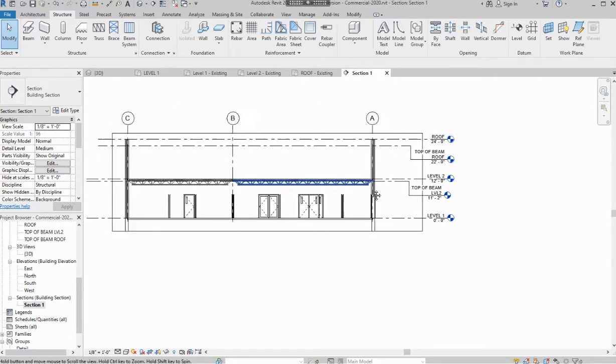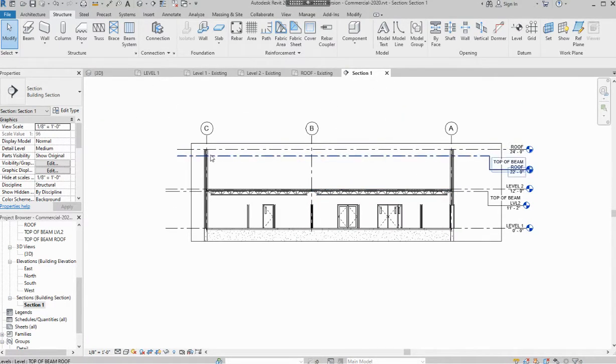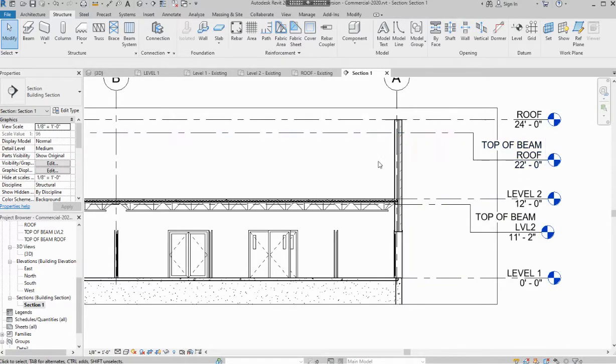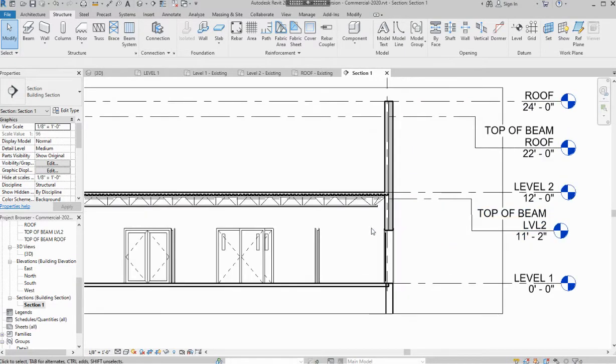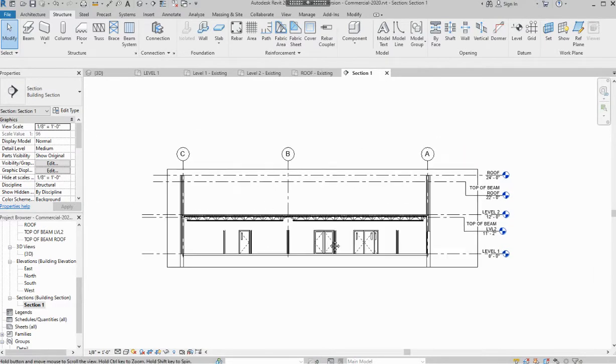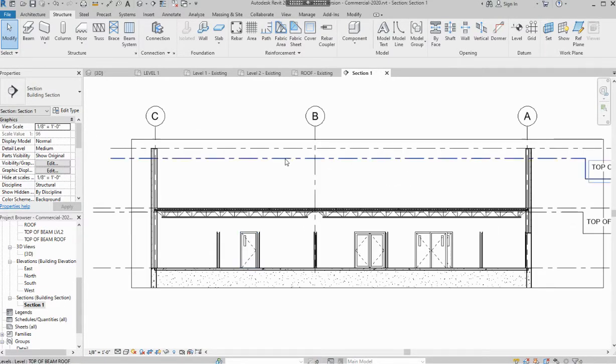So I'm going to let you figure out how to place the roof system up here based off of using top of beam and getting things to line up. And then there will be a video that shows you how to create the insulation. But exactly the same process that we used to place this framing here, I'd like you to use for the roof system. You can use the same spacing, the same series of trusses, just to get a chance to do it on your own. So next we're just going to place these beams, and then I'll stop this recording and we'll do the roof framing.